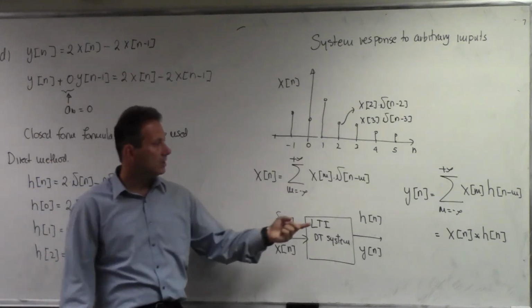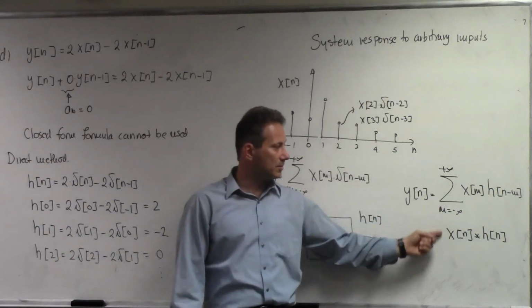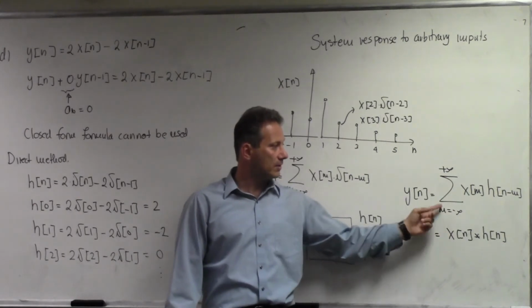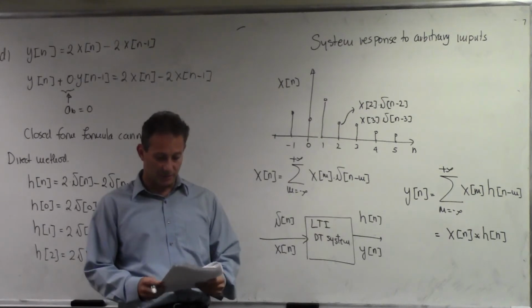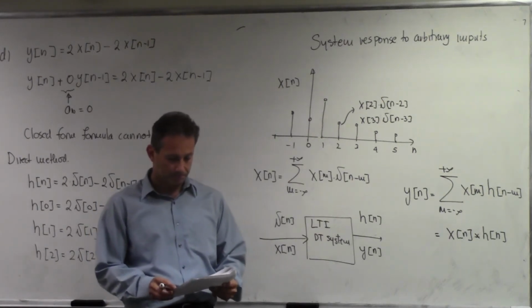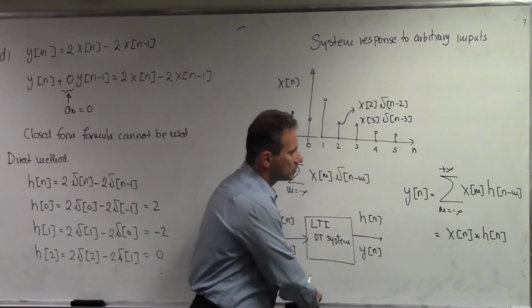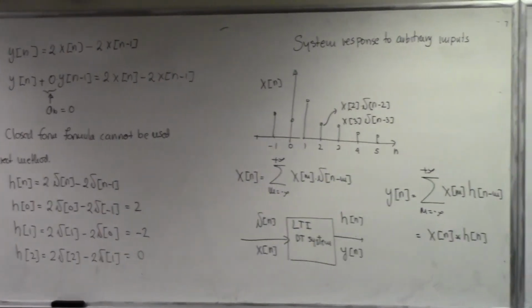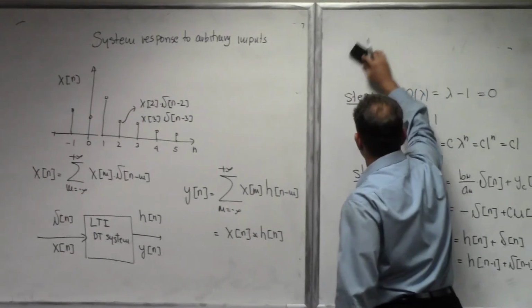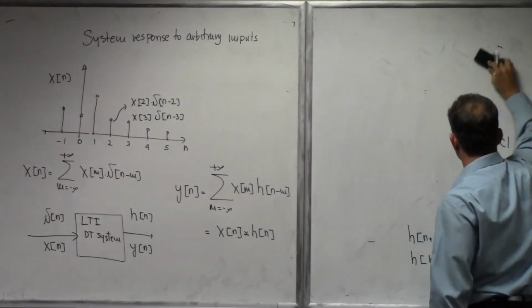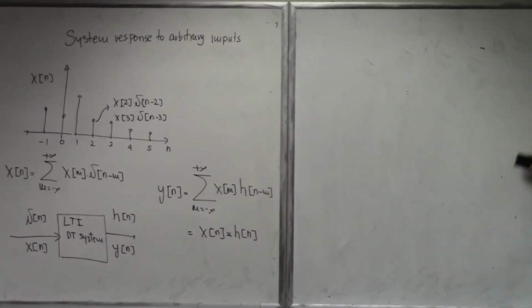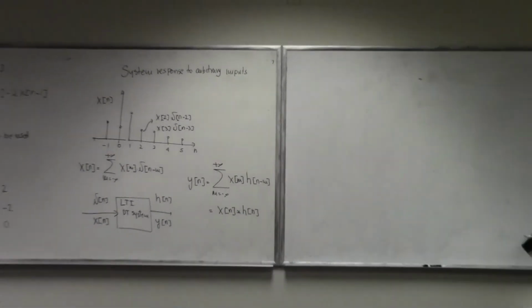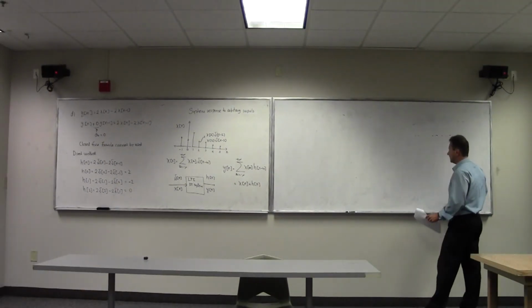And the convolution here is, since we're in the discrete time, it's not going to be an integral, but it's going to be a sum of very similar shape to the convolution integral that we dealt with in the continuous time domain. Now this convolution here has some very cool properties that are very analogous to the properties that the convolution in time domain has. But nevertheless, let's just state them and see if there's any things that are slightly different than what we encountered in a time domain.